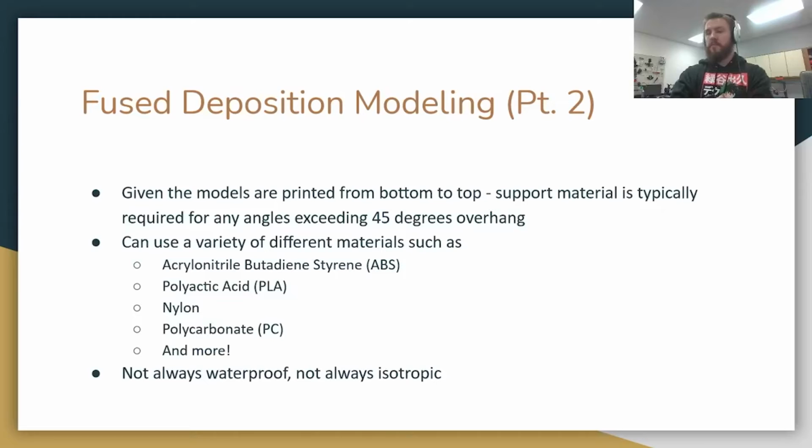If you have an idea for a project that you would like to 3D print, see what they recommend for the material. Do you need something that's flexible and bendy? Is it going to be something that you wear on your face? I know that 3D printing masks was a big thing recently because of the pandemic, and there were certain filaments that you couldn't use, because if they bent, they would shatter when they break, and no one wants plastic shards in their mouth. So these kinds of decisions became very important when choosing the filament type.